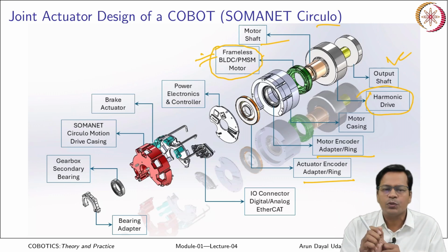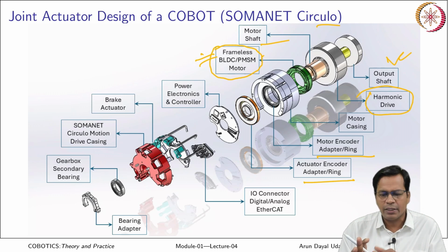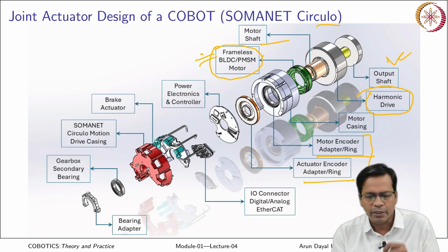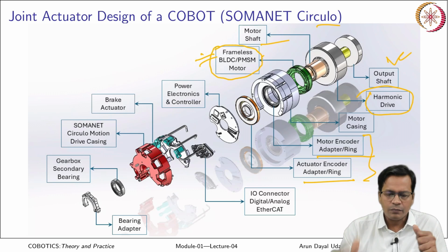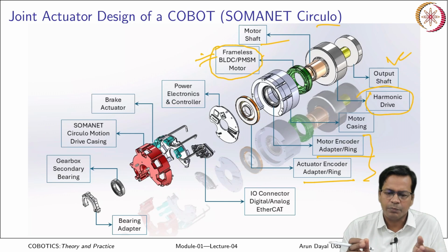So this can be used also, input and output side of the gearbox. If you know the stiffness of the gearbox, you can calculate the torque based on the encoder readings. This is a primary way of doing it, but also it has a live torque sensor which is based on the strain gauge or different technology maybe.